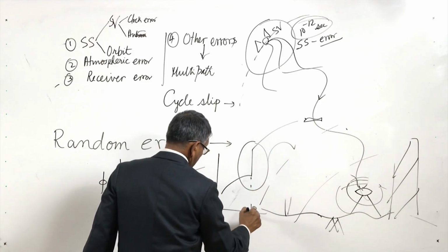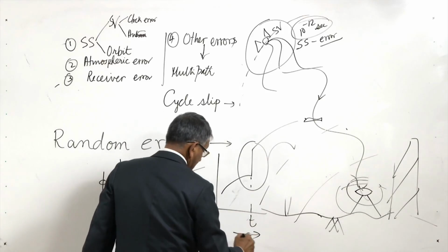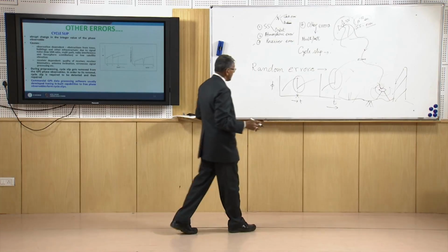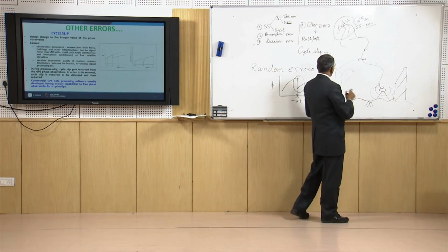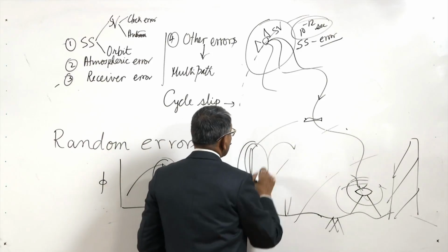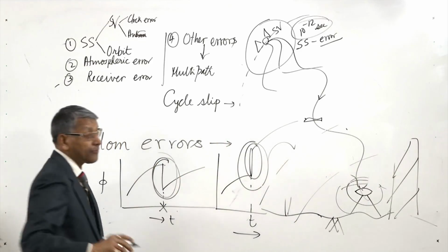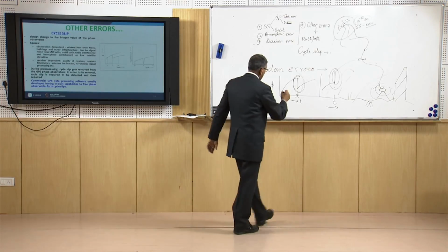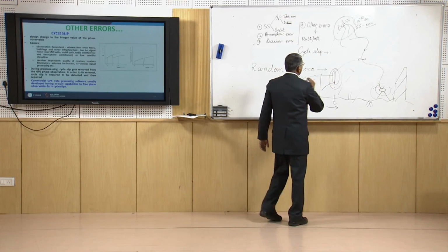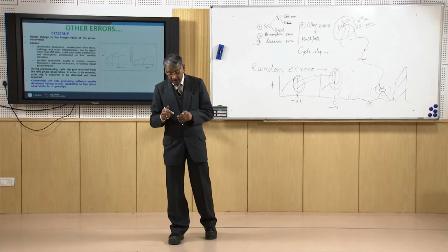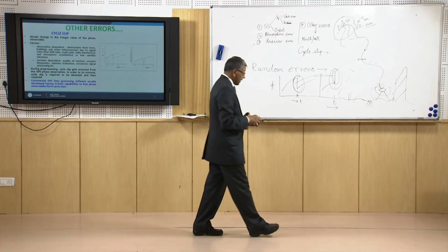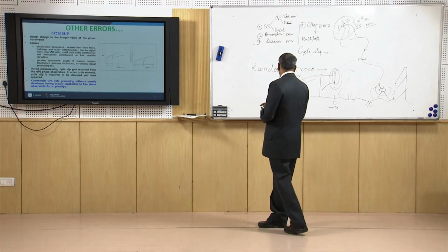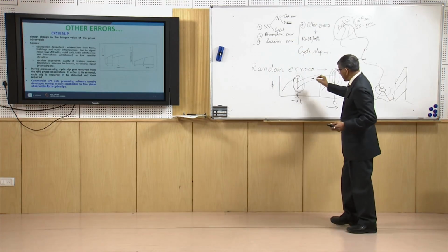Corresponding to that time we can say that there was a disturbance in signal reception, and so there is a sudden increase or sudden decrease in the number of cycles in the GPS phase observable. This phenomenon is known as cycle slip. Now during GPS data preprocessing, we can identify and remove the observation corresponding to this time.